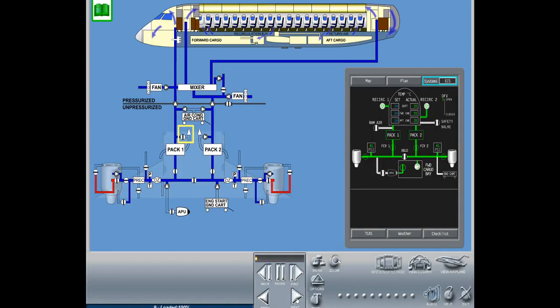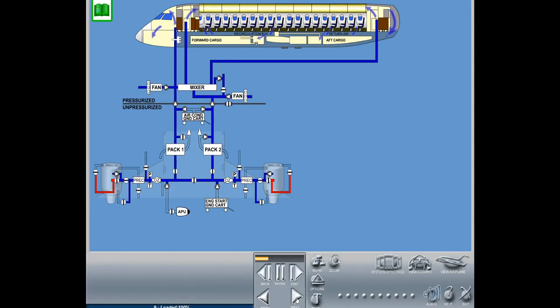The Pac-1 ram air ventilation consists of a ventilation valve installed in the emergency ram air ducting that connects the ram air duct to the Pac-1 outlet ducting. The emergency ram air valve is commanded open anytime the airplane is in flight, and Pac-1 and 2 are commanded off or failed, and the airplane's flight altitude is less than 25,000 feet.